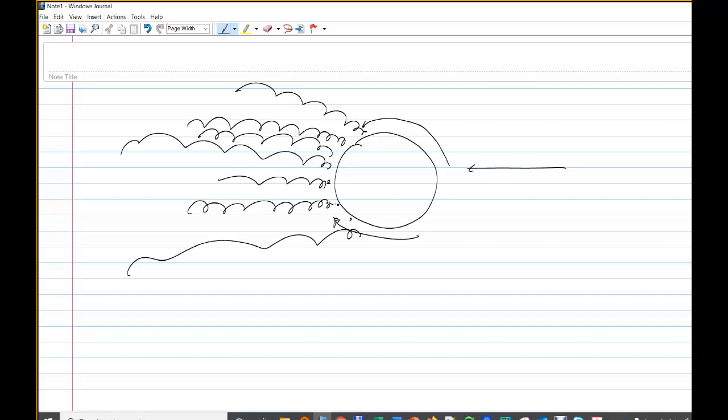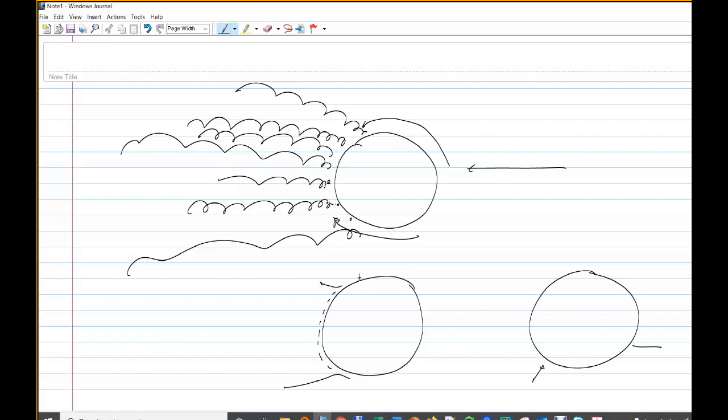And because of that, if you plot the pressure, you have some pressure here, but when it detaches, this pressure becomes negative, or becomes a low pressure. And this pressure also. So if you calculate the distribution of force on the cylinder, you have some force applying here due to pressure, but you have also some force acting on this area. And you have one resulting force that, for example, is in this direction.